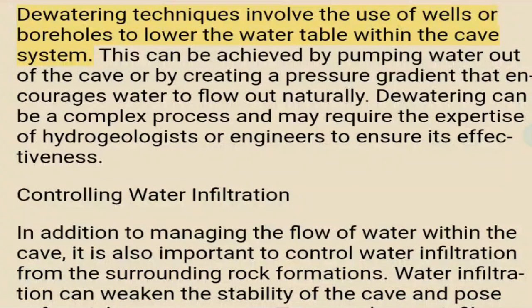Dewatering techniques involve the use of wells or boreholes to lower the water table within the cave system. This can be achieved by pumping water out of the cave or by creating a pressure gradient that encourages water to flow out naturally. Dewatering can be a complex process and may require the expertise of hydrogeologists or engineers to ensure its effectiveness. Controlling water infiltration.